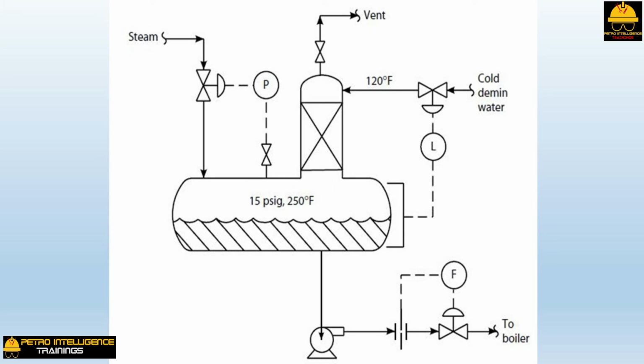Anytime the steam inlet control valve becomes fully open, the deaerator temperature, pressure, and water level will become unstable, and the deaerator stripping section will flood. Flood in the sense that boiling water may erupt from the atmospheric vent.